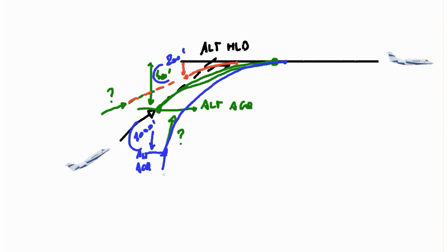It could be that because the climb is very shallow, the aircraft will transition directly into the alt green or the altitude hold function. One thing that has to be said is that the alt acquisition is a function that brings the aircraft, as we just said, from the current rate, from the rate that we have at the moment, so this rate here, we bring it from there, from 800 feet per minute to 0 feet per minute.